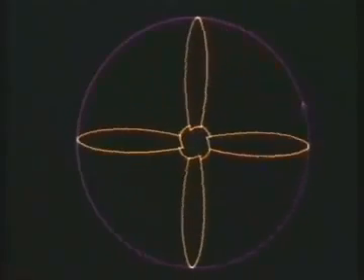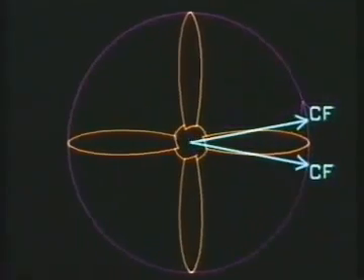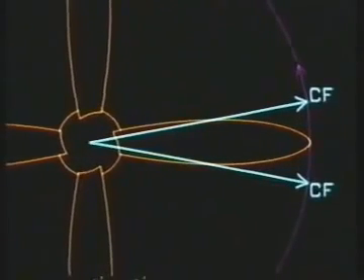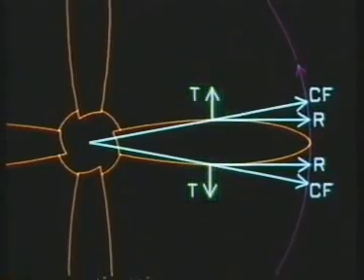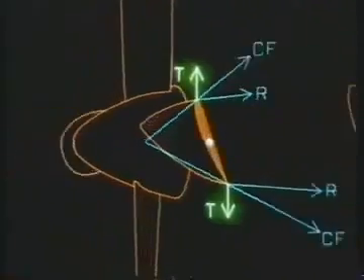Three principal stresses affect propellers, and centrifugal force causes two of them. The first is produced by the radial component, which tries to tear the blades from the hub, and the second by the tangential component, which tries to turn the blades to find the pitch.